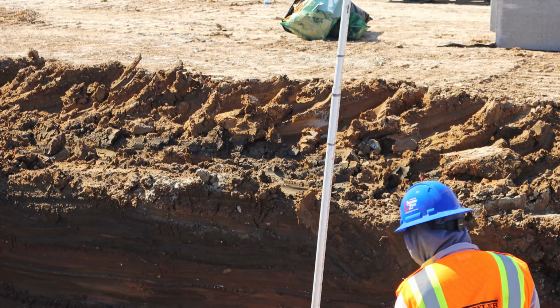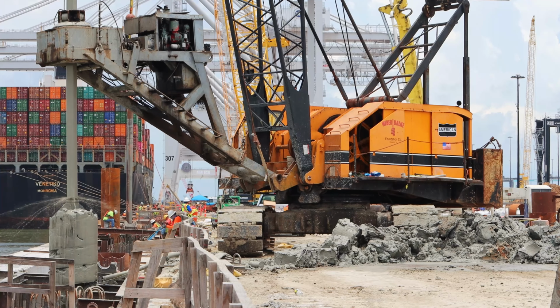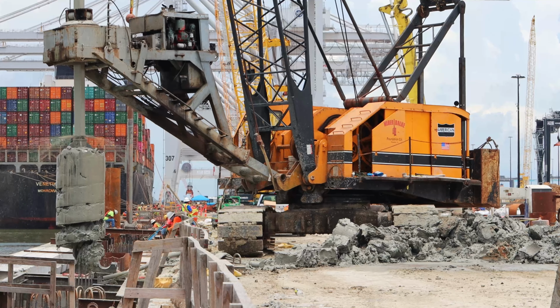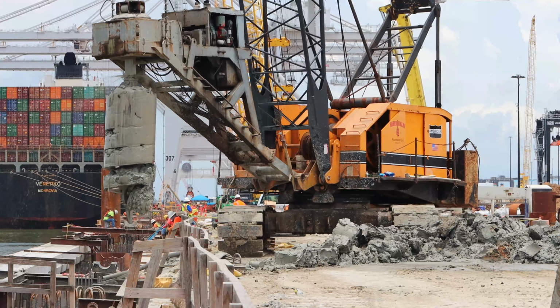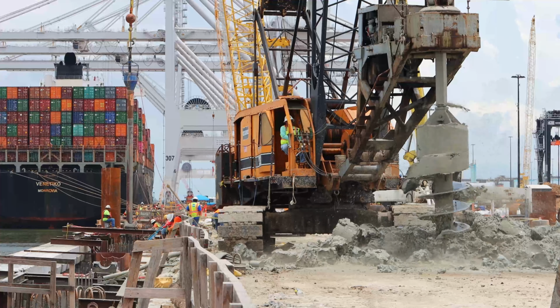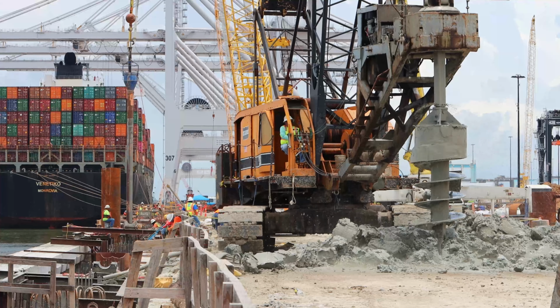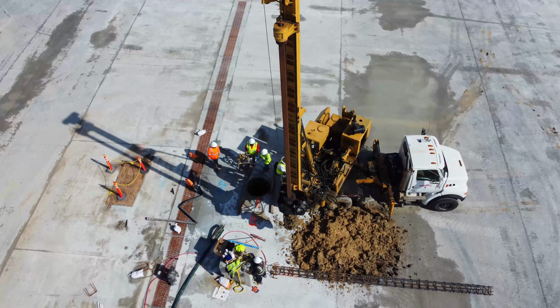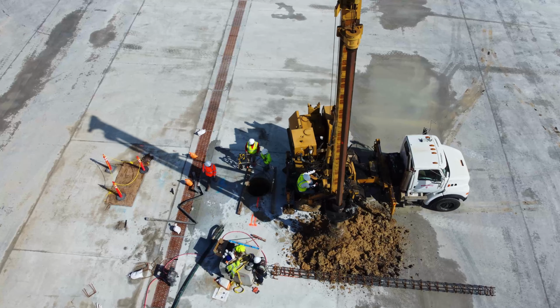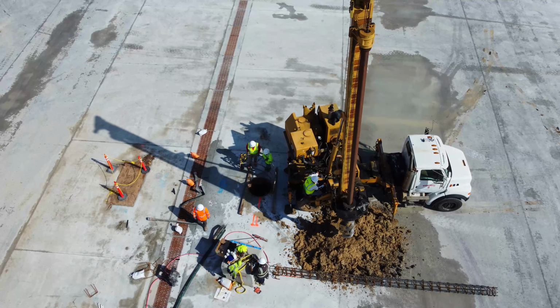At the same time, geotechnical investigation begins. The main objective is to tell design engineers what soil they will be dealing with. During subsurface investigation, geotechnical engineers obtain samples of soil. Typically, drilling rigs are used to bore soil and recover samples for lab analysis.